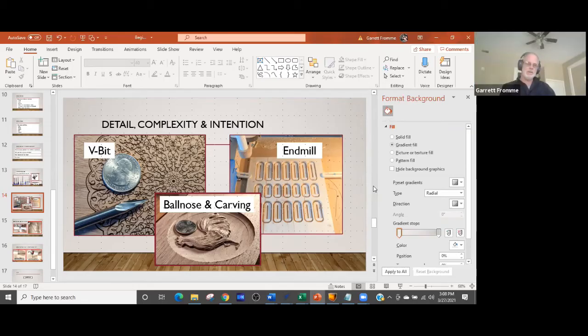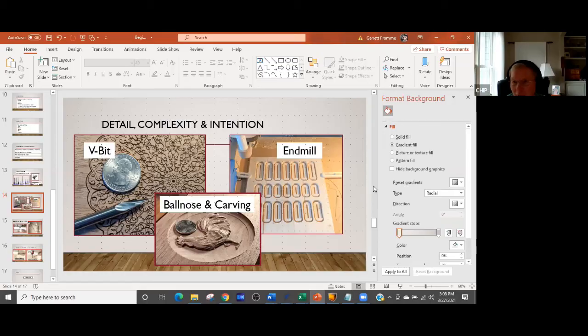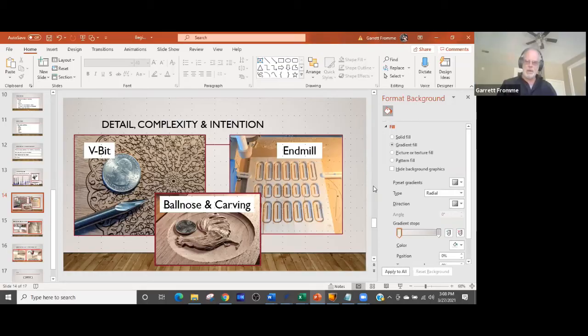Okay, so that's a fairly robust machine. So you should be able to work with your straight router bits. Do I have to ramp them in? Well, yeah, absolutely, because they don't have a bottom cut on them. The rule of thumb is to ramp half the diameter of the bit. When you're using that kind of bit, I would ramp the full diameter of the bit.